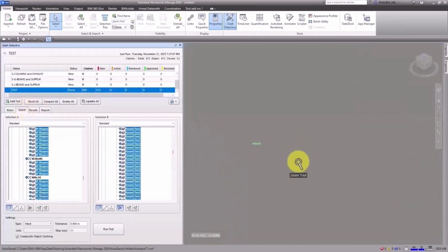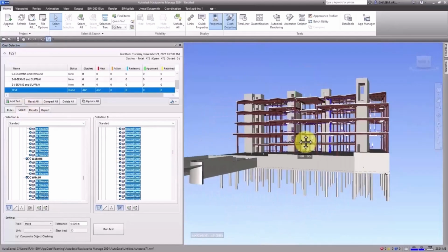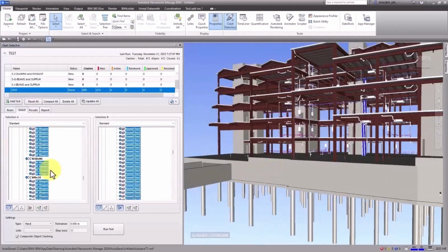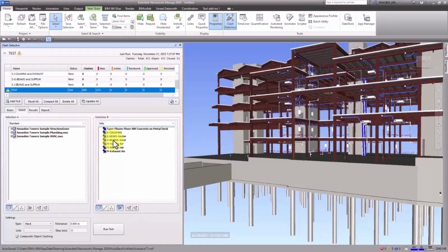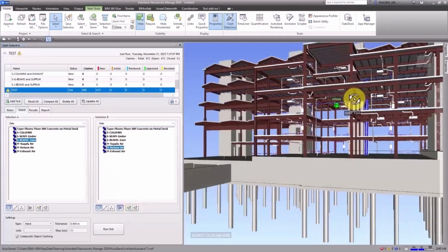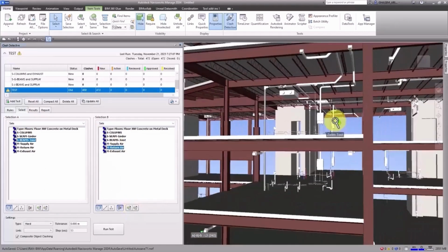Back to here. We have the opposite of it as well. Okay, sometimes here in this window in selection A and selection B, you've selected some elements and now you need to select them in the project as well. You can use this selecting scene. When you use it, you can select the elements in the project here as well. So here are these items which we talked about. Return to set, this one as well. When I put it in set, it will work according to the sets. See, when I select this set, or when I select this one, it will select this set.